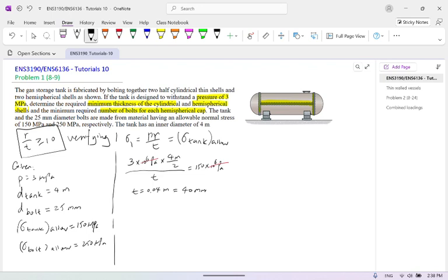So this is something where, and also for the caps of these things, sigma 2 is on the longitudinal direction. I say you should draw by yourself, so I should write down here. Clear? I will not repeat these things because I say I use the knowledge just worked on. So now, of course, sigma T is equal to PR over 2T. So that's equal to sigma, again, the tank allowable.